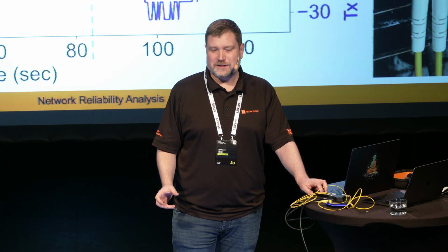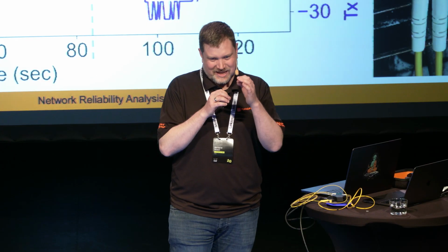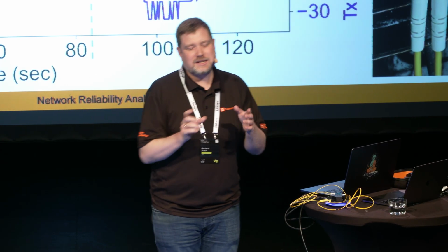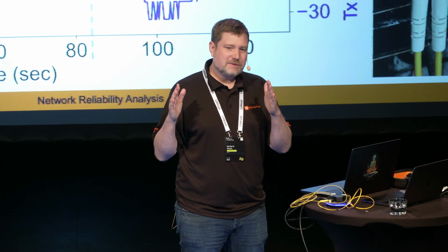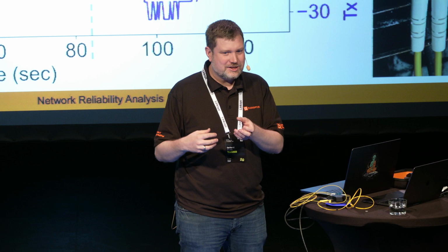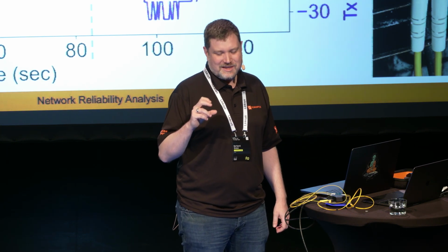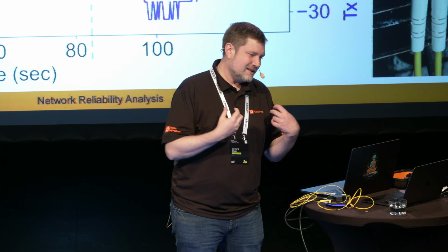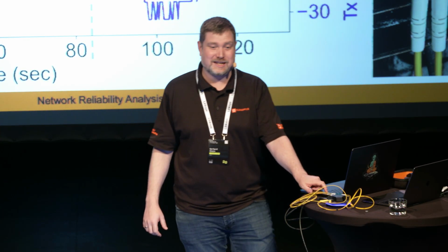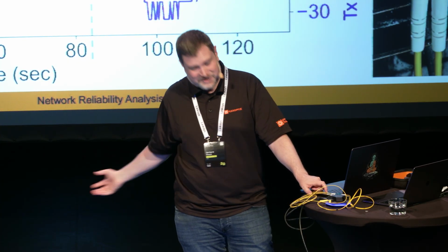I got negative temperatures. Now in this curve it is correct already because I flipped the sign, because your first bit is, you have an 8-bit value you are reading, but usually it is a signed char in C, and the first bit indicates the sign. So it is considered in the standards of the transceiver that you never trespass the 120 degrees. We did that, so we got negative temperatures, which doesn't make sense.